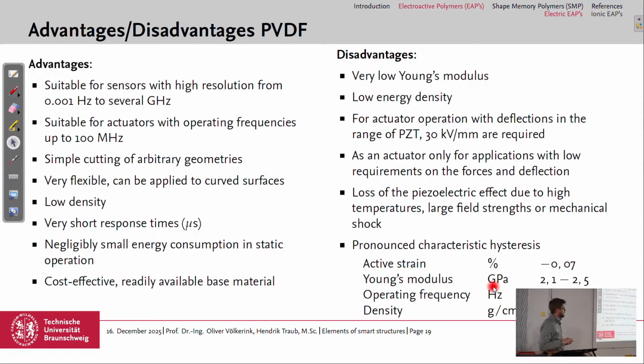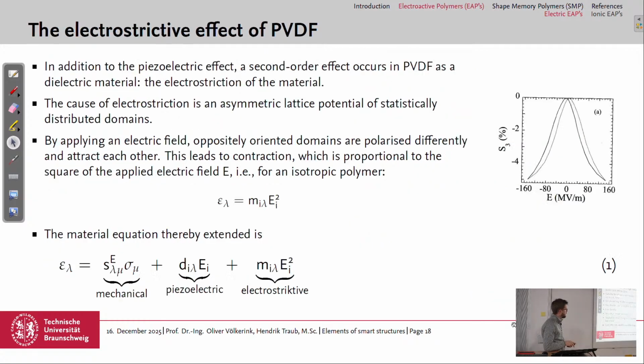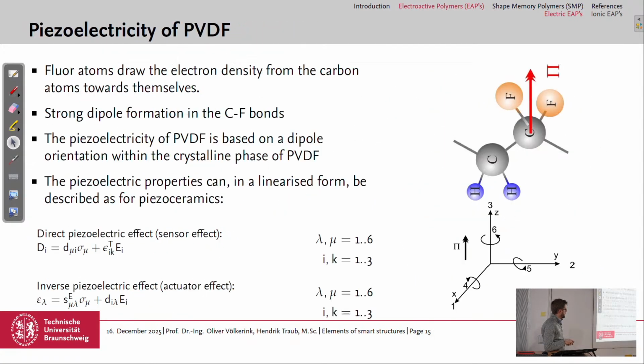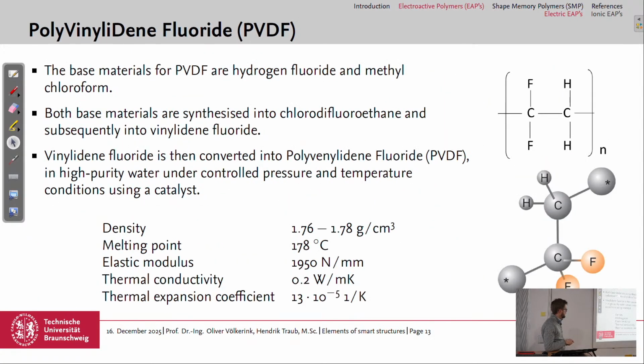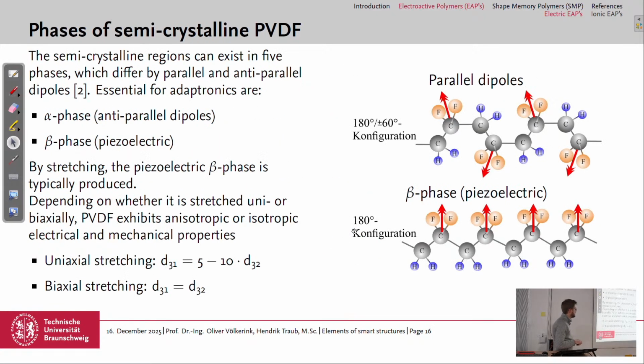Yeah, the Young's modulus over here is written down as about 2. It's similar to what I had on the slide before, maybe slightly higher, depending on the manufacturer and on the data sheet. And density of 1.47. It's also a bit different than what I had on the slide here, but it always depends on the data sheet and the manufacturer. You take the numbers out.